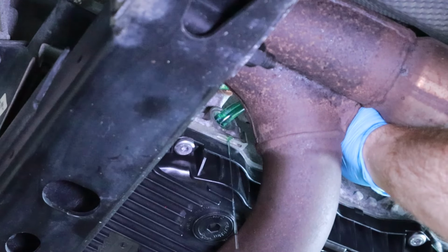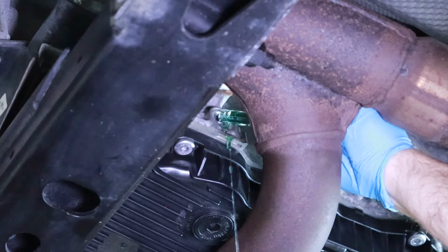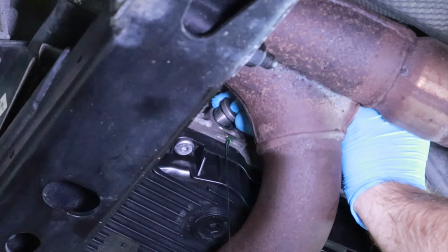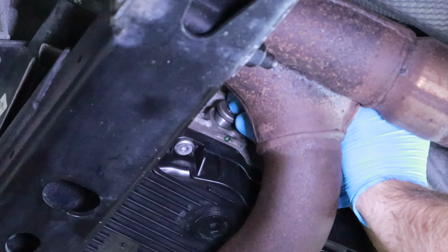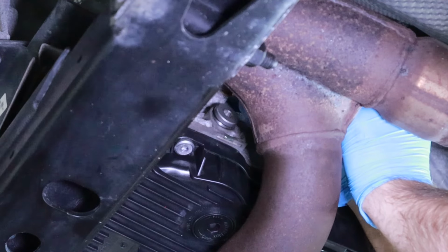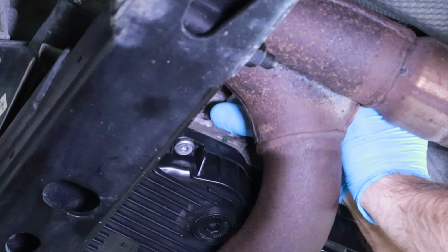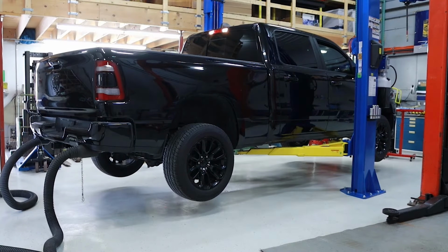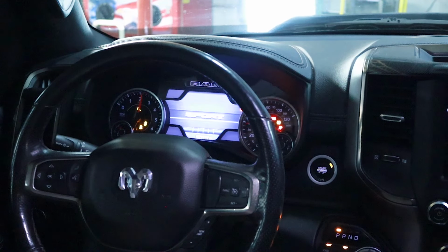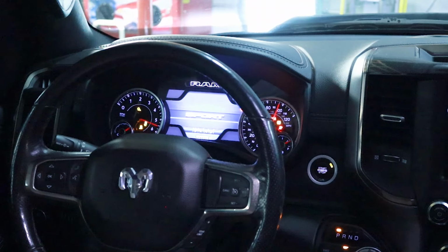Continue filling the transmission with fluid until it begins overflowing from the transmission fluid fill port. Once this is observed, you can reinstall the fill plug to a snug, hand-tight feel. With the vehicle still elevated and in a level position, start the engine and let it idle.